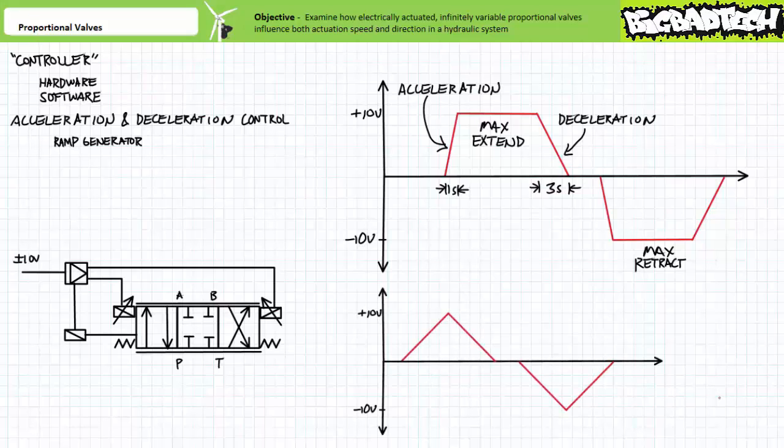If the slope of the acceleration and deceleration ramps were properly adjusted and the distance traveled by the actuator moving at these speeds sufficient to encompass both periods, the applied load would steadily accelerate to maximum speed and then immediately begin to decelerate. An analogy would be starting at a dead stop from one side of a basketball court, transitioning into a slow stroll, moving into a regular walking pace, picking up the pace into a brisk walk, breaking into a jog, then a run, then a full-on sprint by the time you hit center court, and then doing the exact same thing in reverse from center court to the other side.